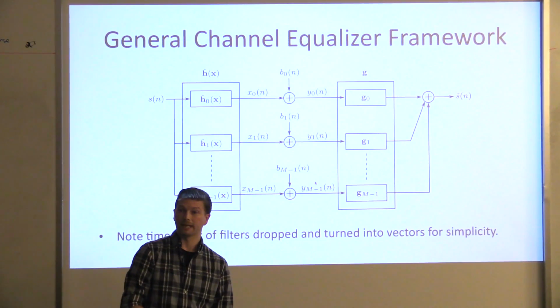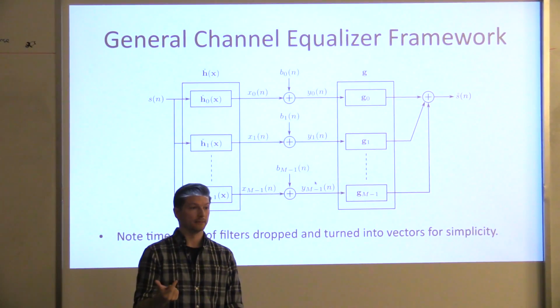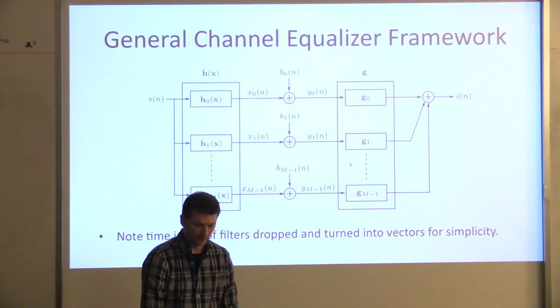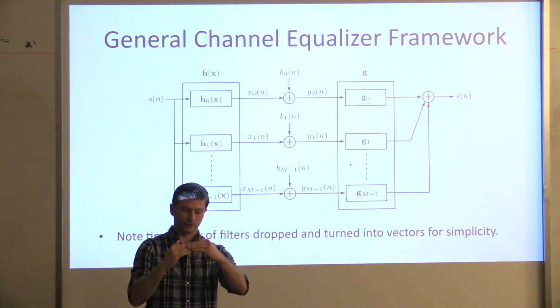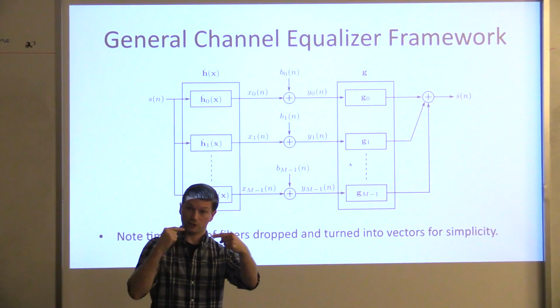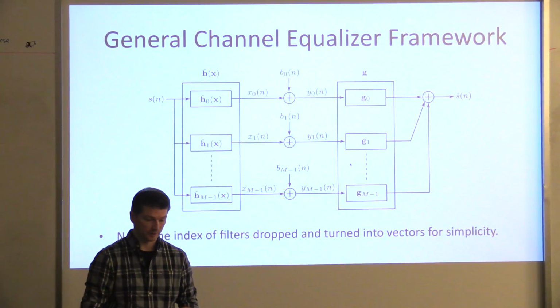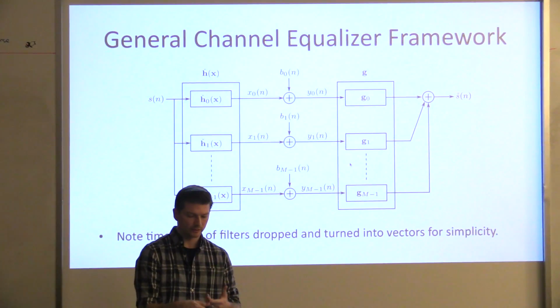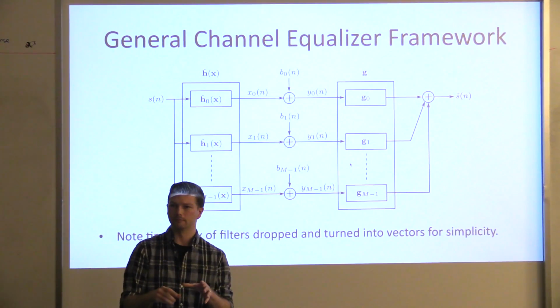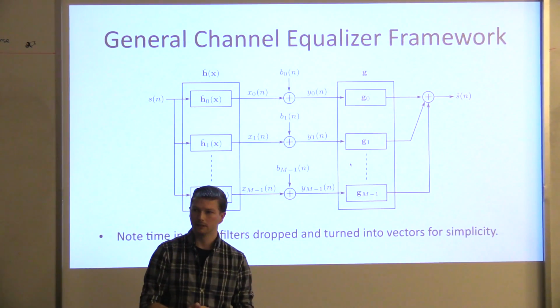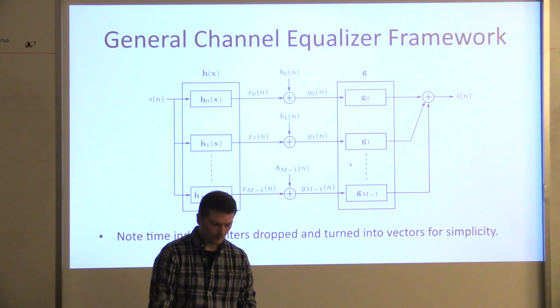Y are the things that we can observe. So Y are the signals that end up being seen by the microphones. And our aim is to derive this set of equalization filters such that when we filter each channel by each filter and then sum their output, we then get an estimate of the speech signal. And all the way through this talk, I'm going to be generally thinking more in terms of vectors, just because they tend to be a bit neater to put down on paper.